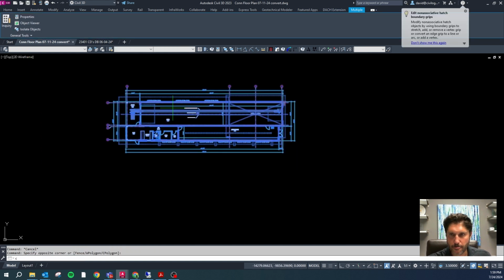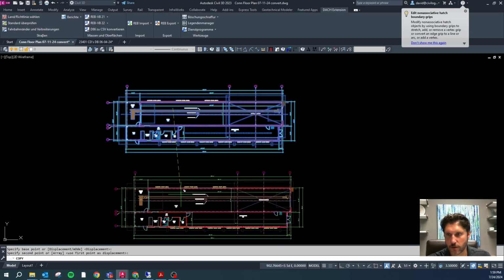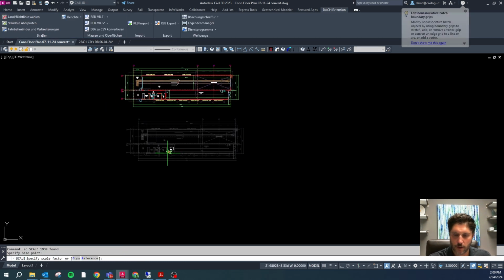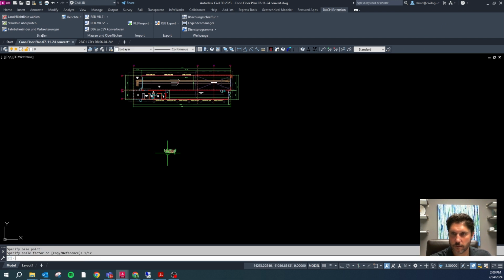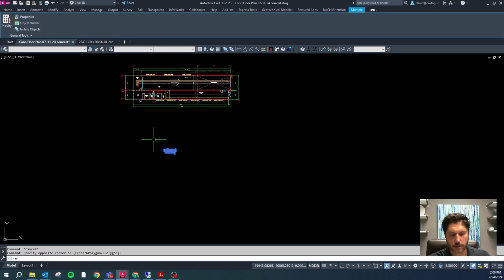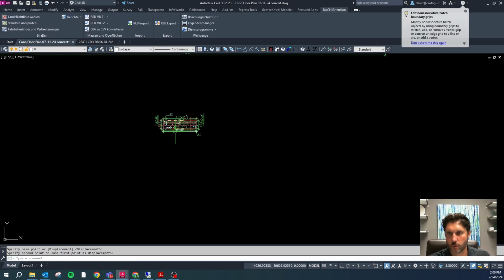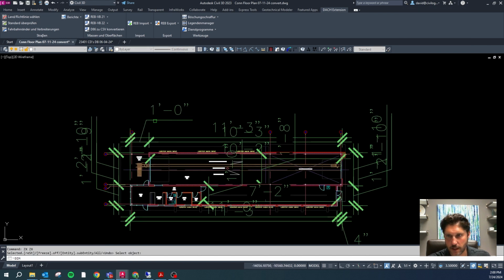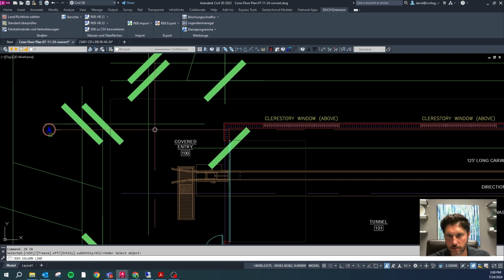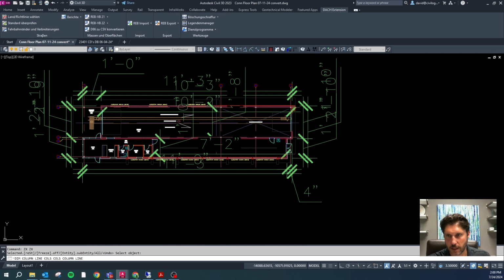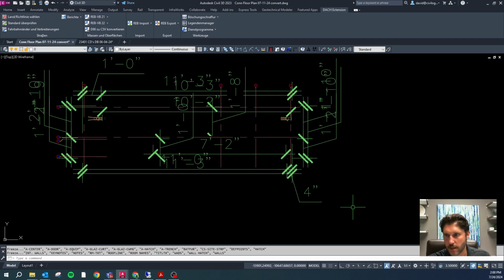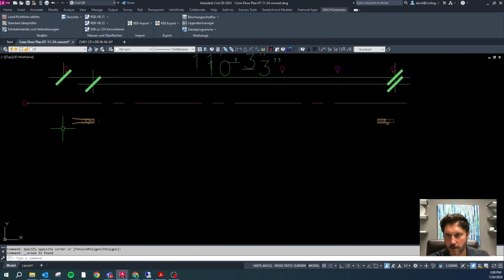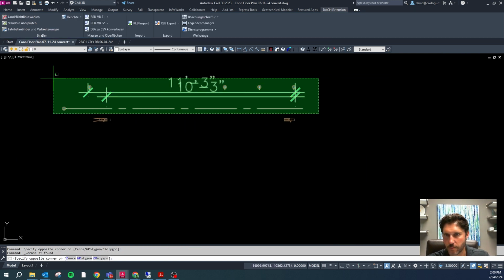So the first thing I'm going to do is copy this drawing. I'm going to leave the other one like that, and then I'm going to scale this by 1/12. Almost all architectural drawings you need to shrink down by a unit of 12. And then let's isolate dimensions and these column line locations and labels. And I really want to delete all of that, but I see that these are in there. I don't want to delete that, so I'm just going to be careful not to lose that part.